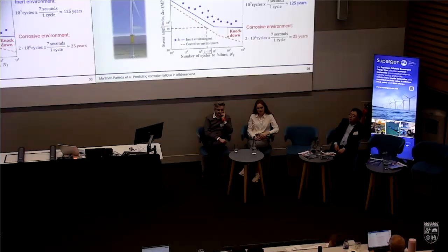However, there's a consensus that this method is highly inappropriate, for a number of reasons. One of them is they're very empirical, as I said. The other one is that the experiments that we're doing have nothing to do with reality, right? Here we're assuming uniform 1D conditions. We have a cylindrical bar, but in reality, corrosion is a very localized process. Also, corrosion is a time-dependent and history-dependent phenomenon, but there's no time anywhere here. And history-dependent means that we cannot use the superposition principles that the standards recommend, or that engineers are using on an everyday basis. So that's what it is.